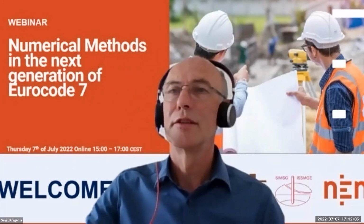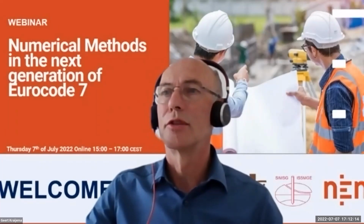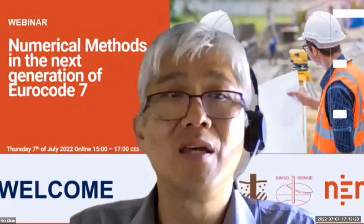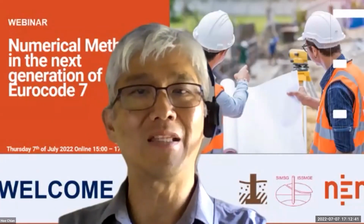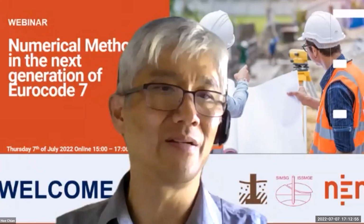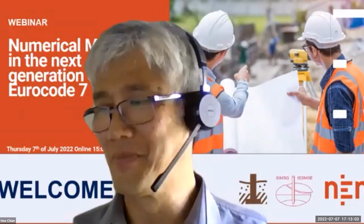Okay, thank you. And last question: sensitivity analysis as far as stiffness is concerned is probably the best tool to assess where we are with our results. So it's more a statement. Do you agree? Well, I guess it's a function of how critical the structure is that you are modeling. A lot of the time, when you design soil-structure interaction, you provide stiffness to the structural engineer. Once you get the right calibration, doubling or halving stiffness, you don't normally get a lot of difference in the design itself. So yes and no, depending on the ground problem, or geotechnical problem, that you're dealing with. I cannot give you an answer of yes or no. I think sensitivity analysis is always a good idea, but not necessarily always necessary.